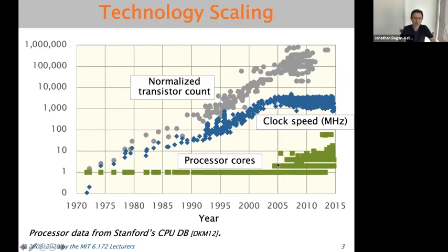But at that same time, you can see, for 35 years, basically every microprocessor chip had a single processor core on it. Starting just before 2005, all of a sudden we started building chips with multiple cores, and pretty soon a huge number of cores, up to at least dozens. And today, dozens of cores are very common in most server chips, for example. So this trend has basically continued to the present. Your phone has 6 to 8 processor cores and about 10 billion transistors in its main chip, but it's still running at best the same 3 gigahertz or so that's been common for about 15 years.